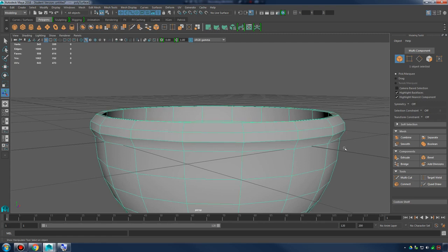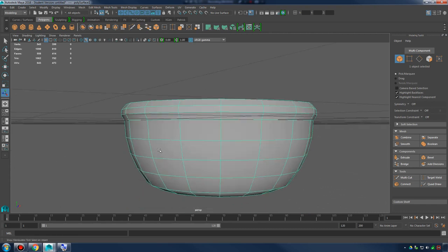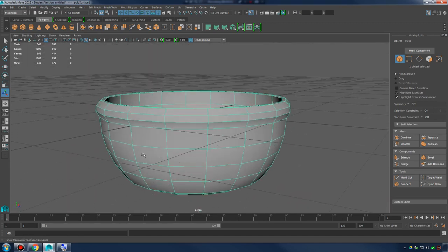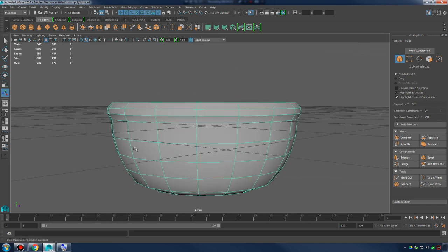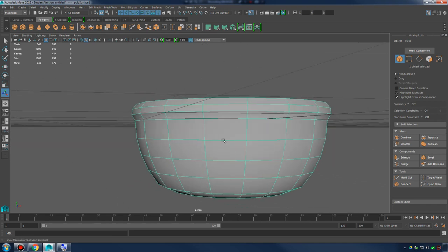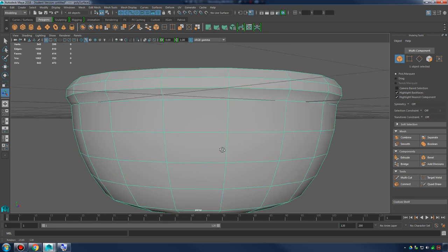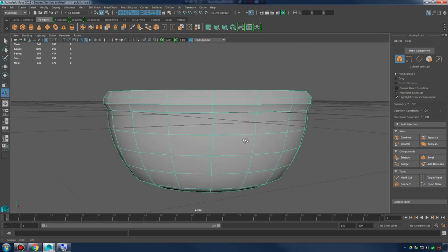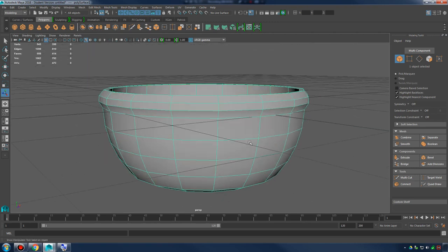And we're really rocking with these extrusions now, learning how to use that extrusion menu. Alright, so the next thing I want to do is maybe add a decorative inlay loop around my coffee cup. But I don't want the little inlay loop I'm going to put around it to be this thick. That's way too thick for the design I want to do. So I'm going to use add divisions to add more faces in a certain direction around my cup. So let's talk about the add divisions tool real quick.